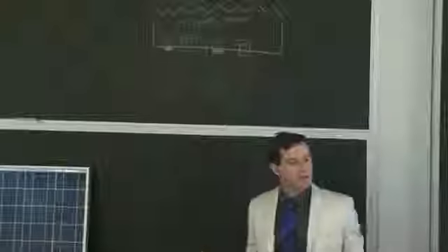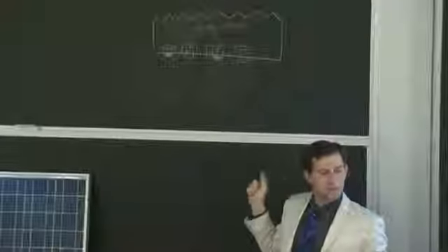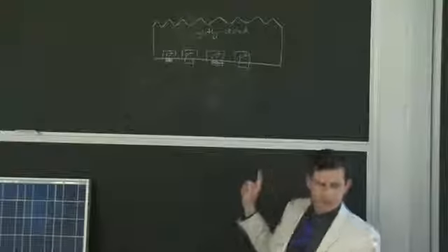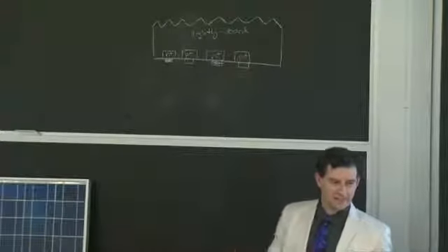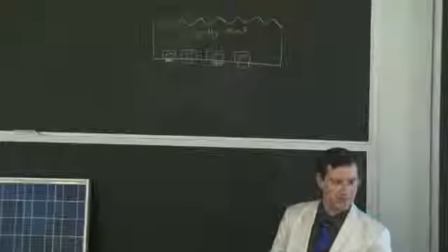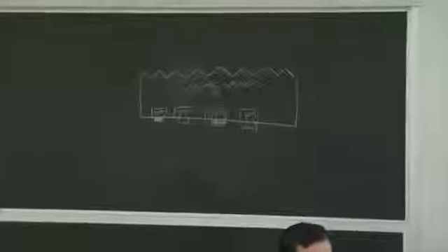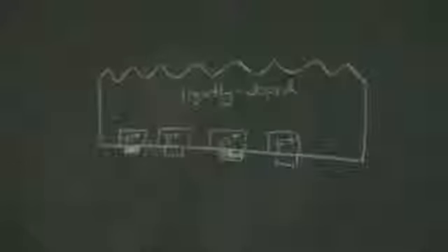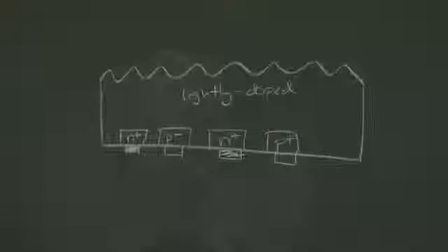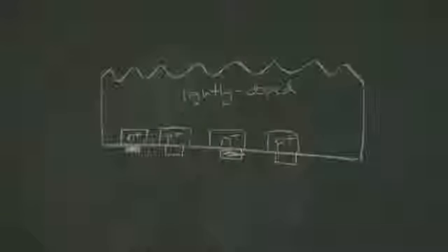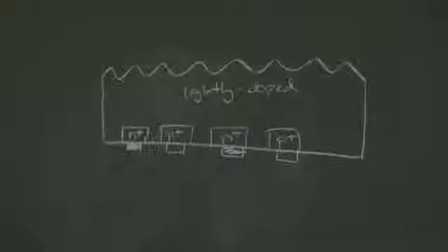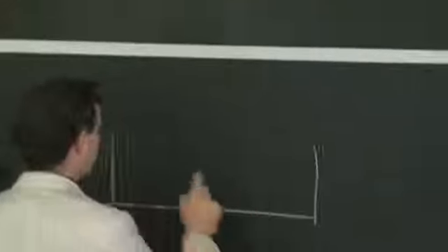Actually, less relevant in this particular case. In most interdigitated back contact cells, it's actually an N-type silicon, lightly doped N-type silicon, just because point defects tend to have smaller capture cross sections in N-type silicon than P-type silicon. So minority carrier lifetime tends to be larger. Another cell design, again looking at cross section, you might have here, this being your solar cell.